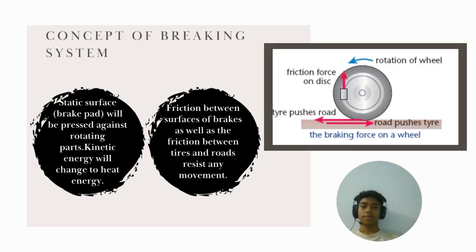Static surface, which is brake pad, will be pressed against rotating parts. Kinetic energy will change to heat energy. The friction between surface of brakes as well as the friction between tires and roads resist any movement.